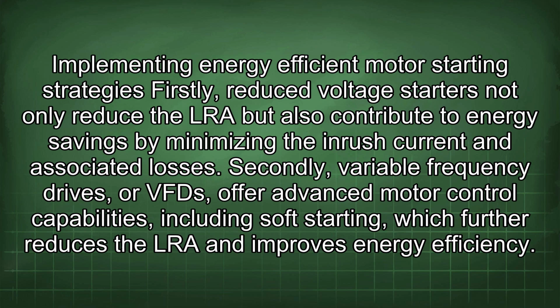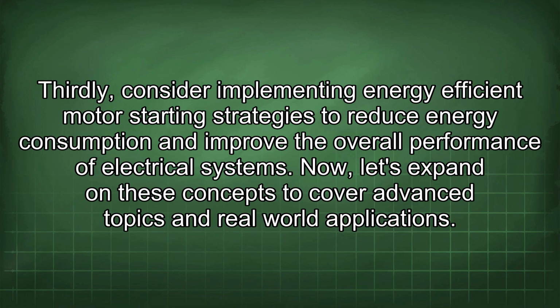Firstly, reduced voltage starters not only reduce the LRA, but also contribute to energy savings by minimizing the inrush current and associated losses. Secondly, variable frequency drives, or VFDs, offer advanced motor control capabilities, including soft starting, which further reduces the LRA and improves energy efficiency. Thirdly, consider implementing energy-efficient motor starting strategies to reduce energy consumption and improve the overall performance of electrical systems. Now, let's expand on these concepts to cover advanced topics and real-world applications.